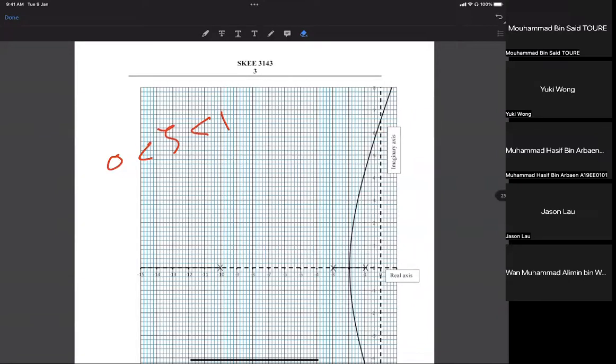So we have to find the over here. This is where K critical and zeta equal to 0. And this one is the breakaway point, where K will give you zeta equal to 1. Critical damping, not critical gain.